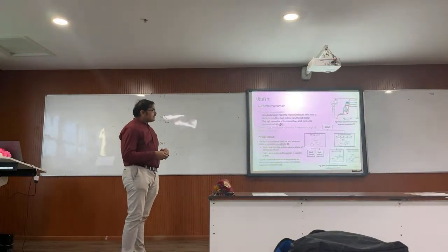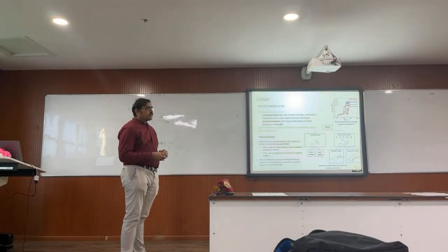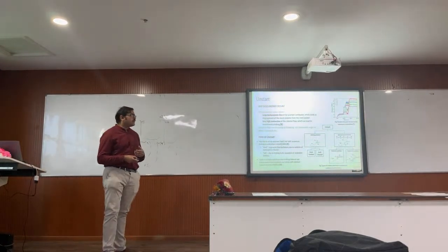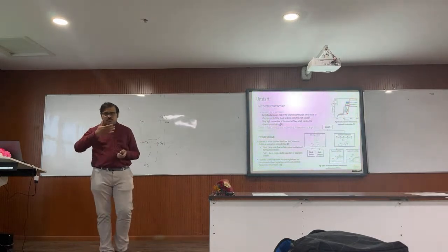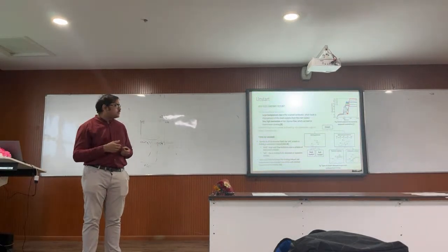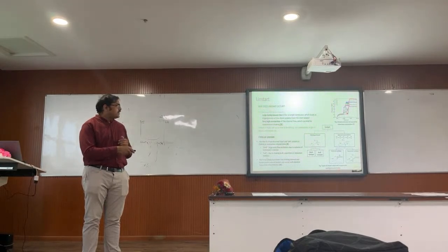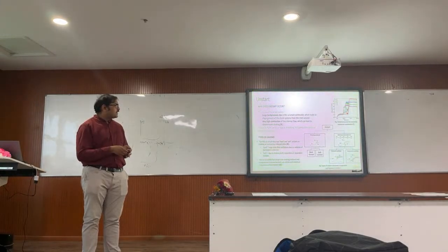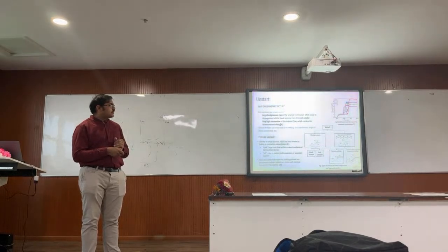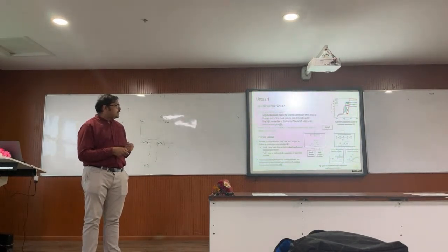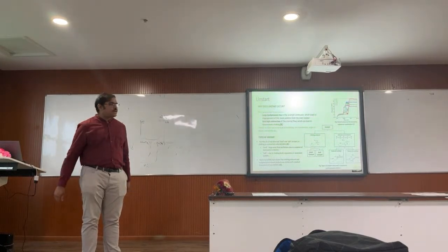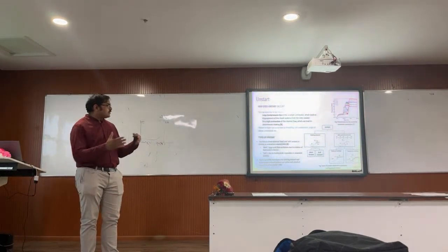Sometimes this unstart can also be caused by severe shock boundary layer interactions. Shock boundary layer interactions also affect the flow. They affect the way the streamlines go into the duct. And if the shock wave boundary layer interaction produces a very large leakage into the duct, then the flow just leaks out, and that also leads to unstart. Such kinds of unstarts are usually termed soft unstarts, while hard unstarts are more from a geometric perspective. The contraction becomes high.